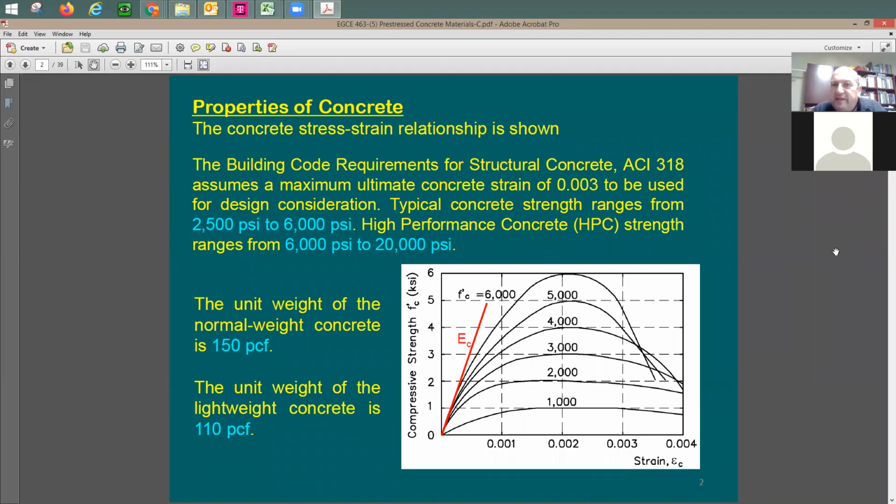You understand that you're going to be having here higher strength properties, generally speaking. According to the previous example that we have discussed, we're going to 270 KSI for the strength of the rebars. So we're not talking about 60 or 90 or 100. We're really working here with high strength materials. So you need also to bring to the picture here really strong concrete. You're not going to go here with 2500 PSI.